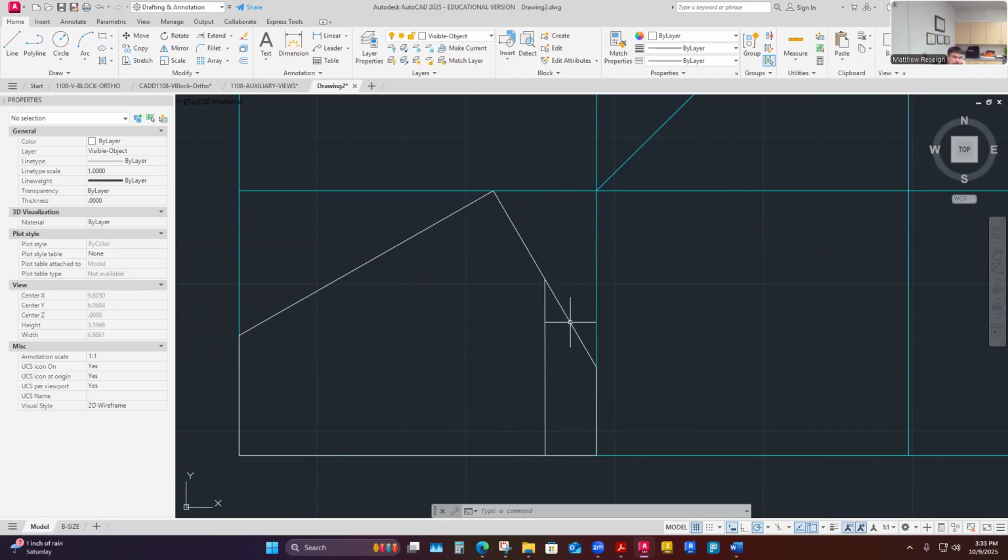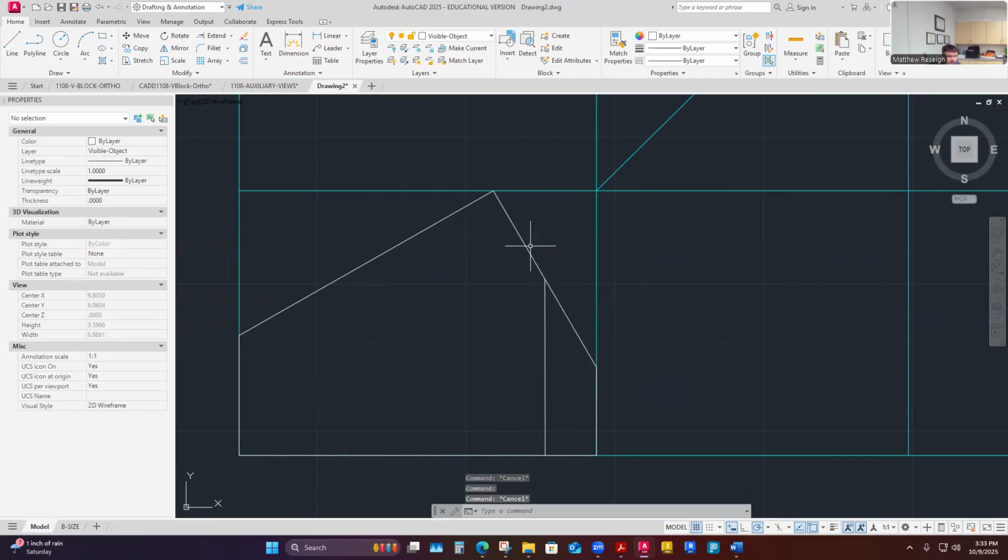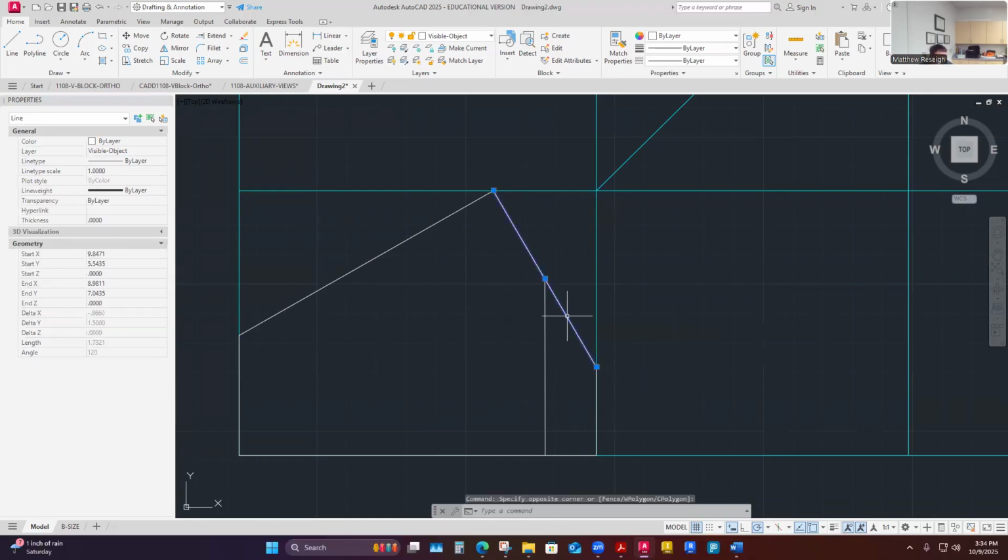Even though this is one line segment, I do pick up the true length of the entire surface, because that's my view plane. I'm looking across that surface, and so I do have its boundary where it lives. It lives from three quarters up from there, and then it was 30 degrees over, and it hit the top that was 2 1/4 high. So that is the boundary of the surface. But I have two different things going on here across this line separation. I've got true length, and then I've got foreshortened length here. That's weird, even though I've drawn it as one continuous line, and it is in this edge, the surface that's going to be my projection plane for my auxiliary view.